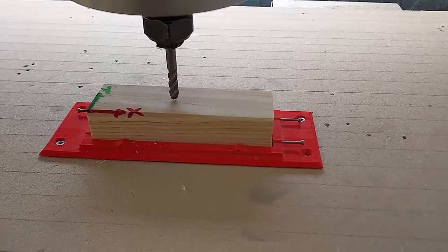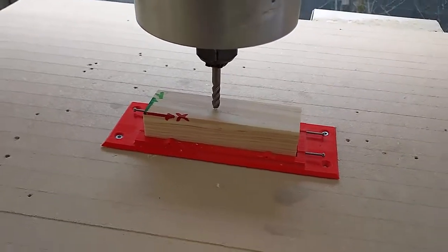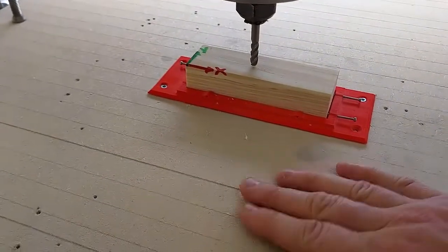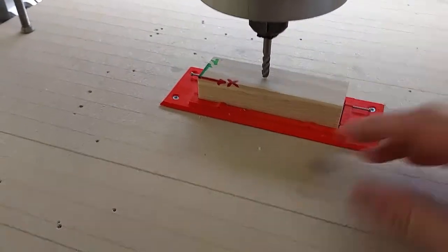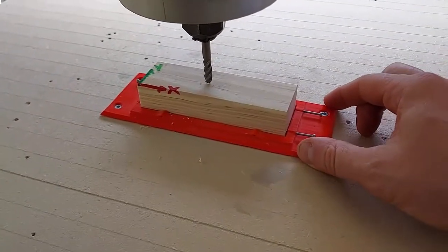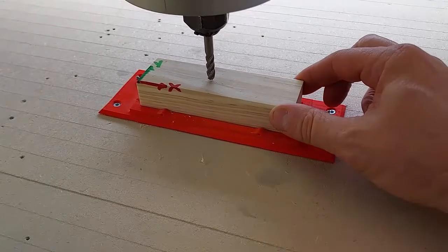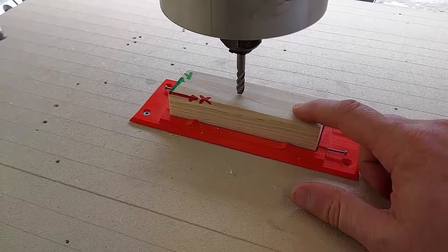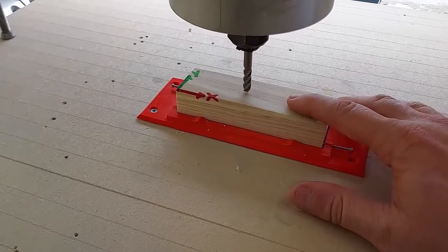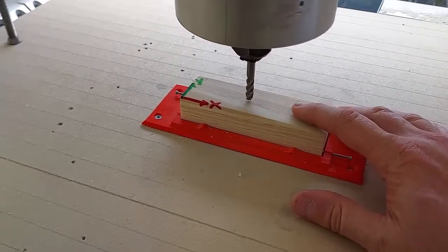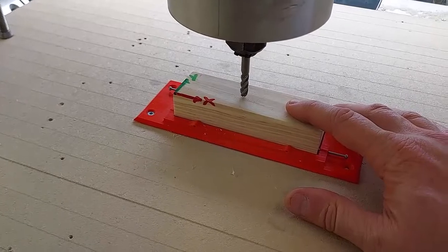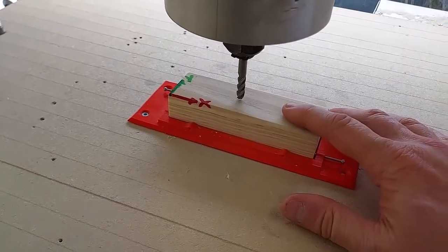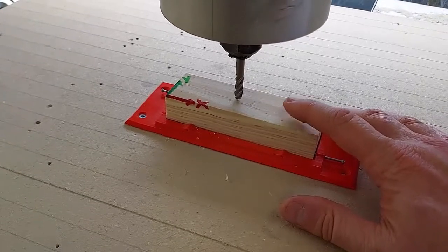Now, before you run your G code, you always want to make sure that your workpiece is secured to the table or platform here. In this case, I have a 3D printed custom fixture that I made for this block. But sometimes you're going to want to secure your workpiece to the spoil board. Sometimes you can just screw it in. Sometimes you can tape it. There's clamps and other sorts of fixtures that you can use. But for this particular project, for my students, we use this 3D printed fixture.